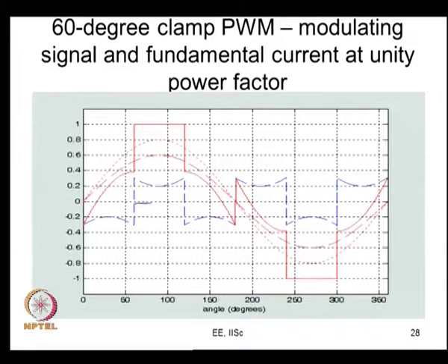Now, the loss is 0 here, and you would actually have your switching loss going like this. You might actually have it going like this. So, where the switching loss would have actually peaked, here, that you have avoided. So, you have saved a lot of switching energy in this region, and therefore, you have managed to reduce the switching loss.